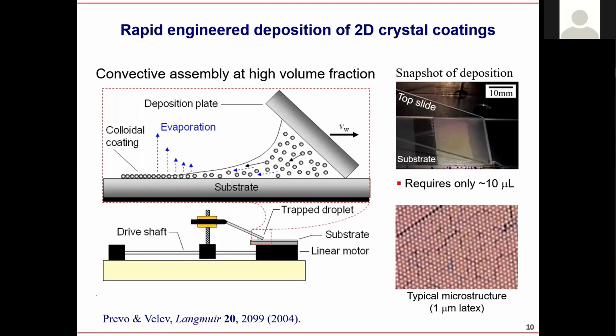Single layer crystal. Hexagonal close packed. This will be hexagonal close packed. Great. Can you have some other type of structure, hexagonal or not? Why is it hexagonal? Because the particles are spherical. So when they're packed together, they make a hexagonal structure. Aha. So when you pack particles, the highest packing efficiency is obtained when they're hexagonal, right? Can you obtain another structure in this type of deposition or not?